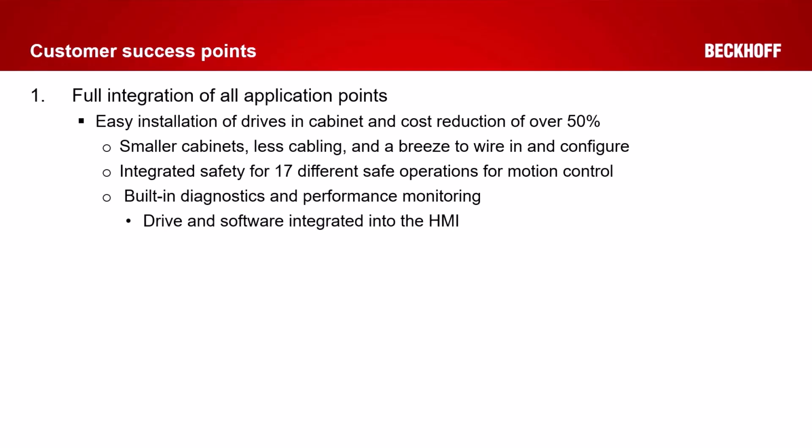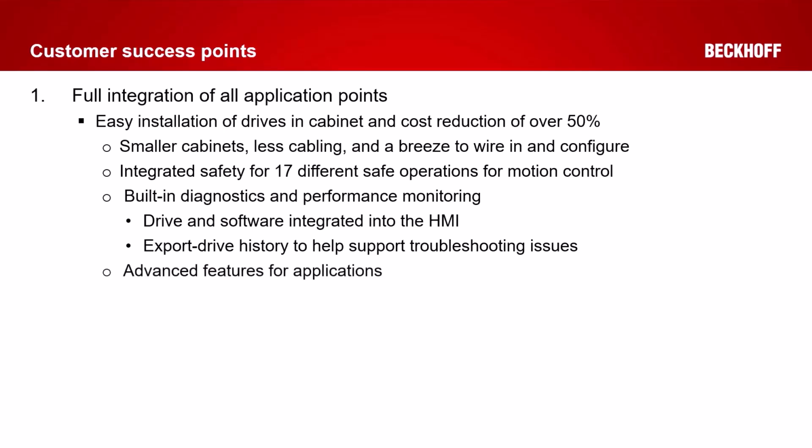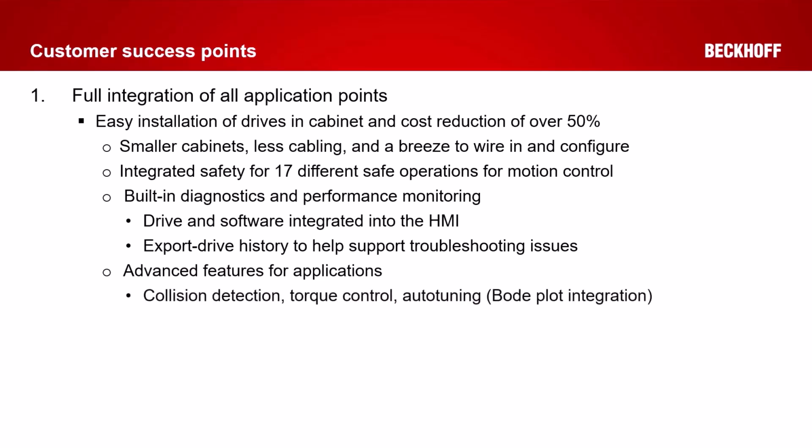The drives are integrated into the HMI. You can export the drive history, so if you need help with supporting or troubleshooting an issue, it's easily done. There are advanced features built into the drive's functionality for collision detection, torque control, auto-tuning with Bode plot integration, and EtherCAT is one of the main reasons why it's so successful.